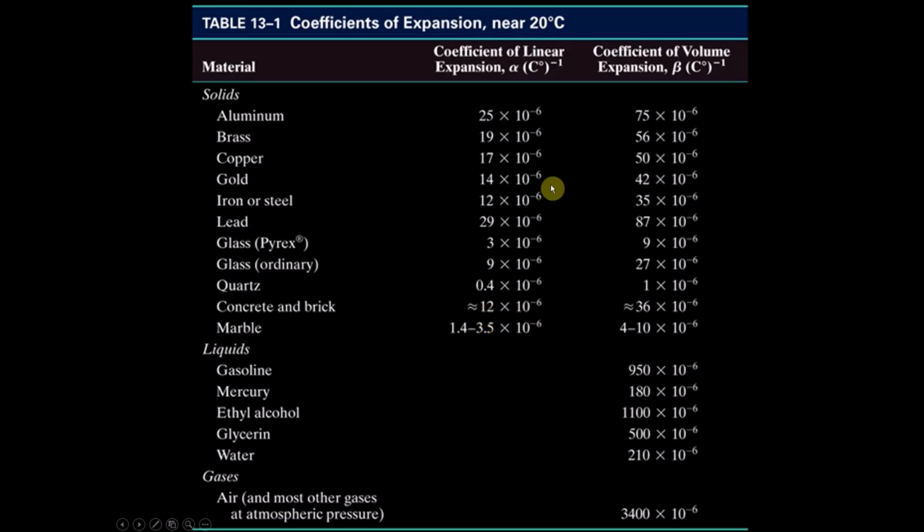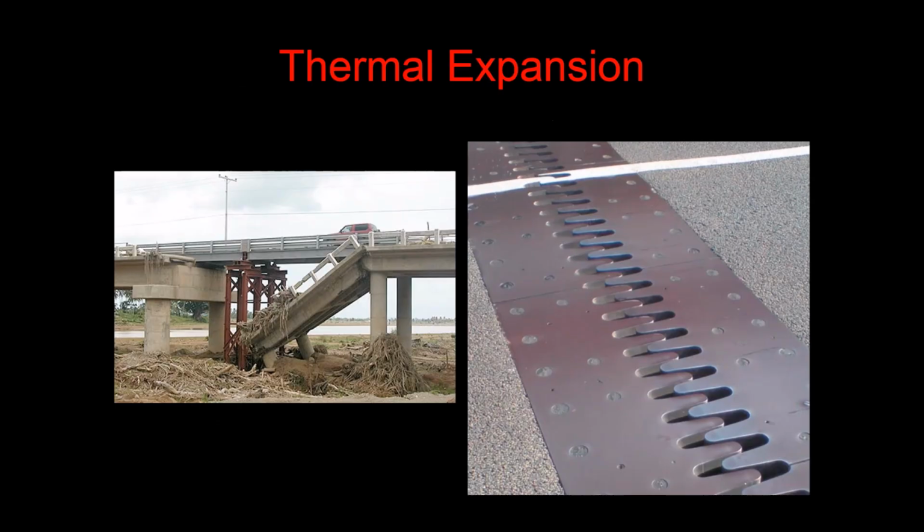This is why reinforced concrete with steel bars through concrete works so well. But they still expand and contract by some value when they're exposed to differentials in temperature. And this means that if you don't have some kind of joint to allow for this expansion and contraction, you will probably see mechanical failure and the collapse of your bridge or whatever other device you're looking at.